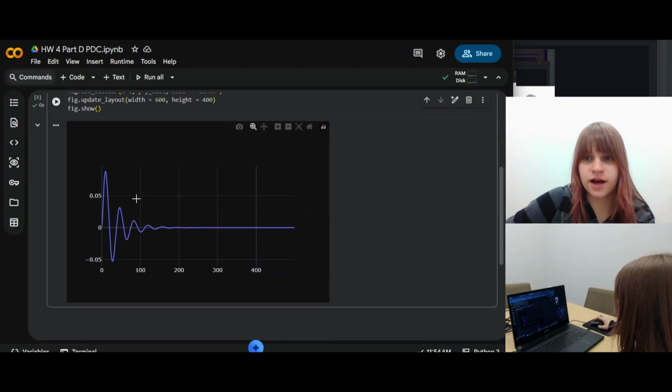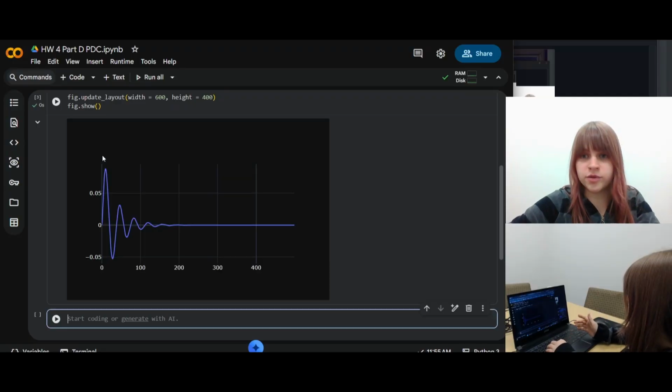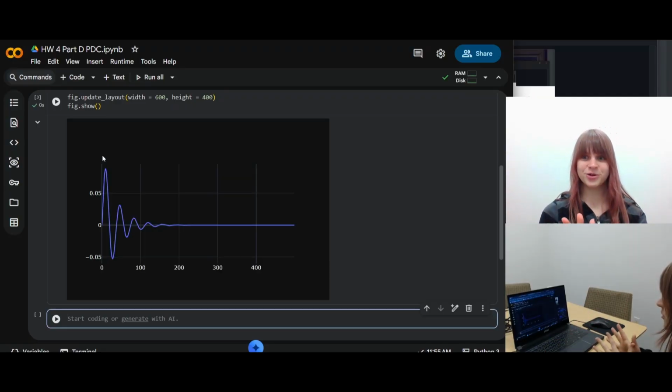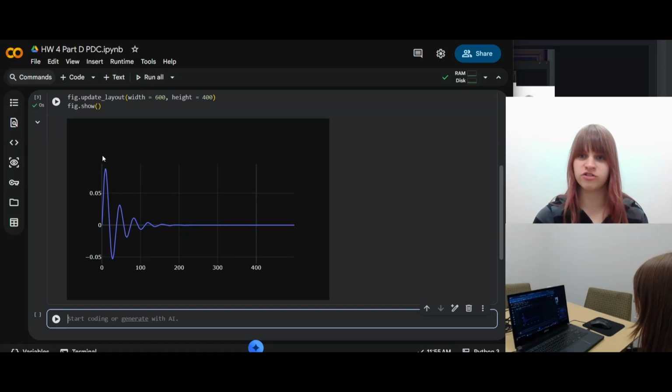So basically we have our disturbance and our system oscillates a little bit, but because of our servo control for our cascade controlled system, it levels out relatively quickly after only a couple minutes at basically 0. And now we want to look at the outer loop disturbance. Or sorry, I said outer loop disturbance. What I meant was, I guess it's the same thing, but looking at an outer set point change. So if we changed that reactor temperature set point at some point.